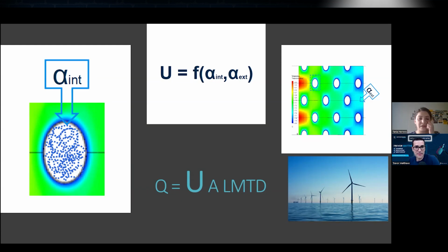Yes, and something also important that I want to mention is that we want the refrigerant to cover the whole wall of the tube. That's why we also need high velocities, because if the velocity is too low, then we will have a separation. At the end of the day, we have a mixture of phases in the tubes, because we have a phase change.